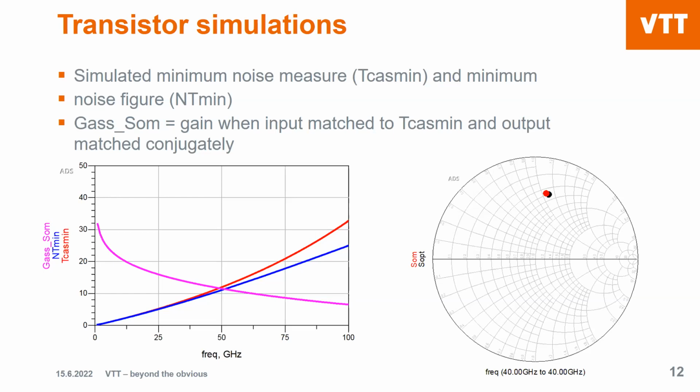That is minimum noise figure or noise temperature. That is given. But you need to use the equations in the previous slide to calculate the infinite cascade number. If you cascade an infinite number of these transistors and make a matching network with ideal components, you end up with the red curve.